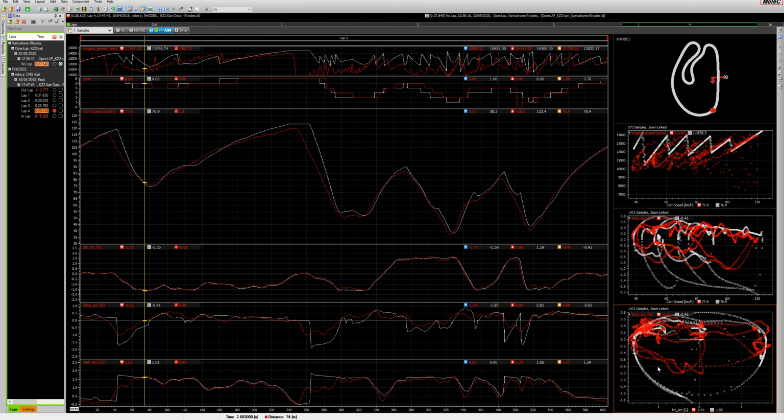So this either means that karting tires can generate way more lateral grip than longitudinal, or that there is more braking potential to be found in the real kart. Either way, an inclusion of a braking pressure or a braking pedal force limit is an easy update to the code and will allow OpenLAP to simulate braking system limitations.